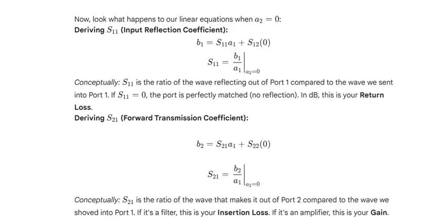Deriving S11, input reflection coefficient, is shown here. Conceptually, S11 is the ratio of the wave reflecting out of port 1 compared to the wave we sent into port 1. If S11 equals 0, the port is perfectly matched, no reflection. In dB, this is your return loss.